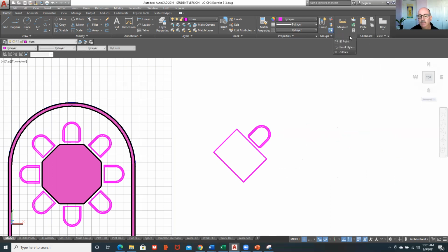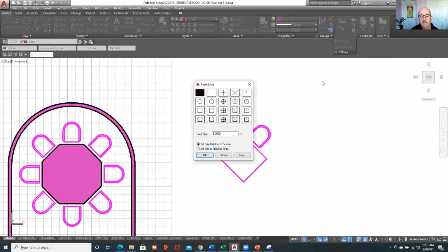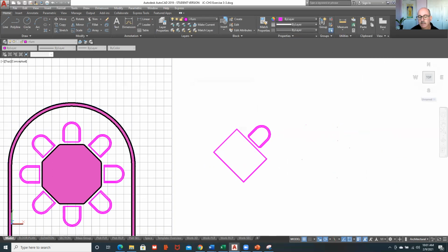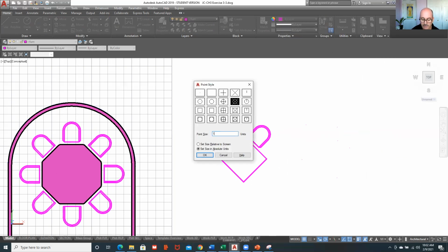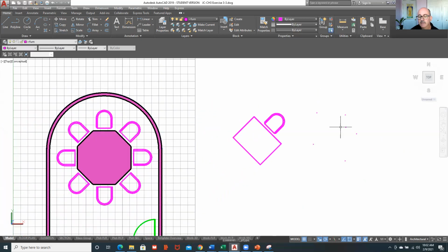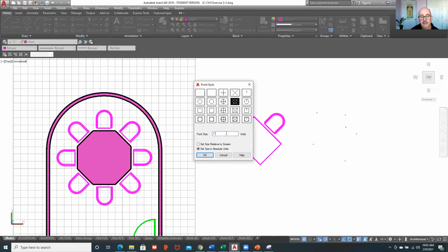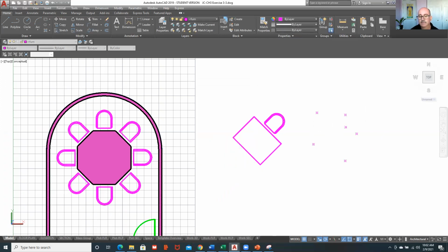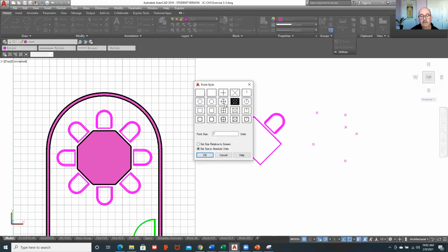To make them visible, you go to point style, and then you set a point style. I like to use absolute units, and I typically make them like 1/4 of an inch. Those are too small. Let's go back and make these, let's just make it 1 foot. And so you can see as you increase the point style sizes, you can then see them. And so point styles, let's say 3 feet. They get bigger. And then you can also go through and change the way they look, squares.